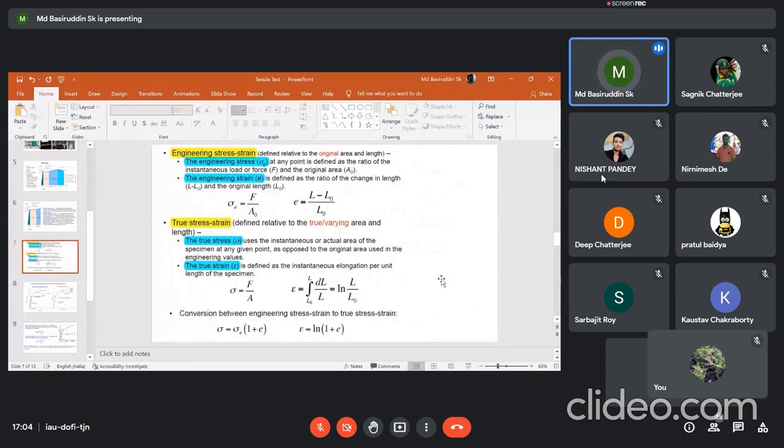Okay, so I think those particular things I already covered, like the measurement of the stress and strain. Here, considering the true stress and true strain, you can follow these particular equations and correlate them with the engineering stress and strain. But one limitation is that you can follow this equation only up to the UTS level, where you can use the initial gauge length and the final gauge length of that test material. But when it goes beyond the UTS level, then